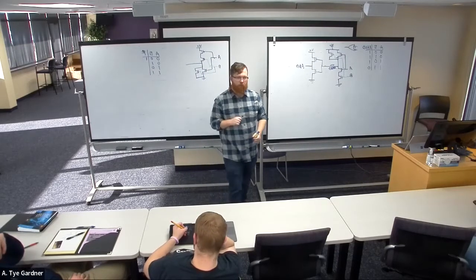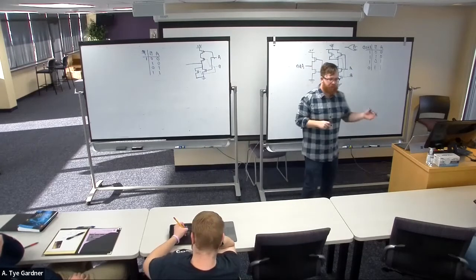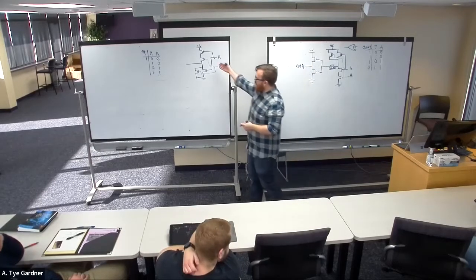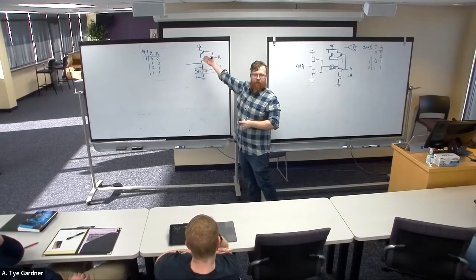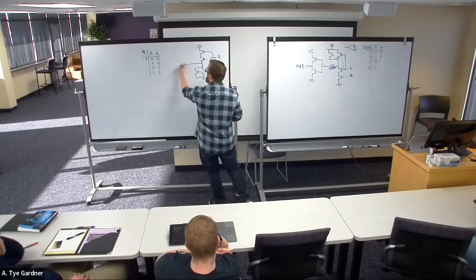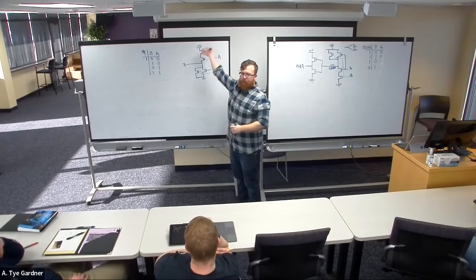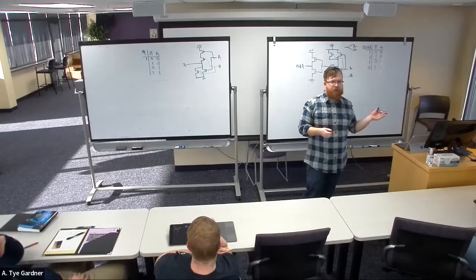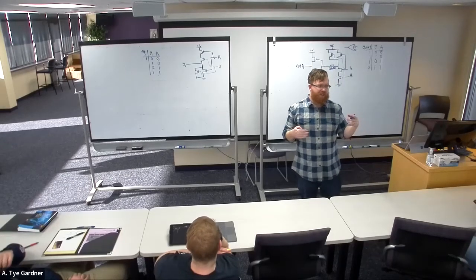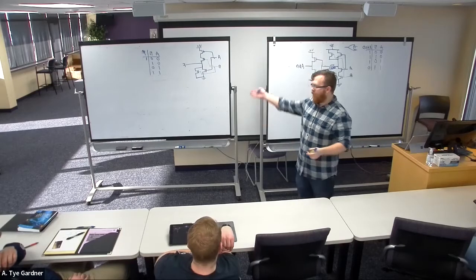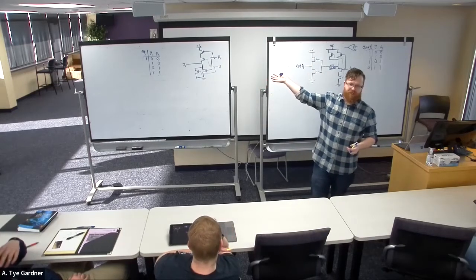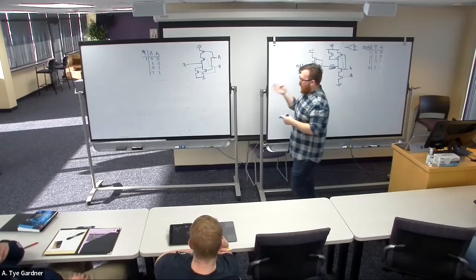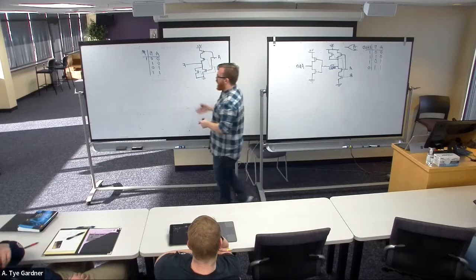Well, now I know for a fact that I can't, because I just enabled the only way that I can see VCC, right? The only way that my output F can be connected to power is if both of those are on. So I know the other situations are going to be not one. We could potentially end up with a situation where it's neither one nor zero, right? Where I messed up that drawing before, and it could end up in a situation where we don't know what it is because it's not connected to anything. So we want to make sure that the others make sense, right?